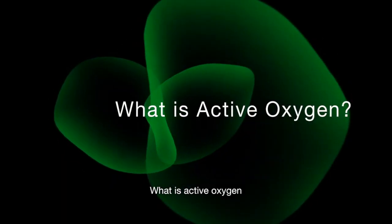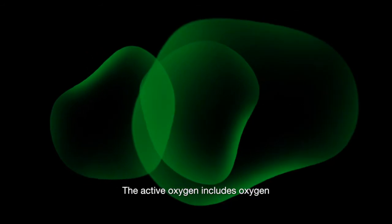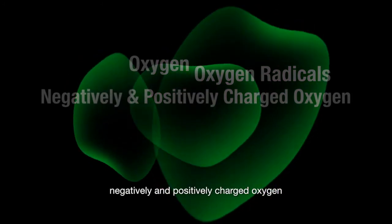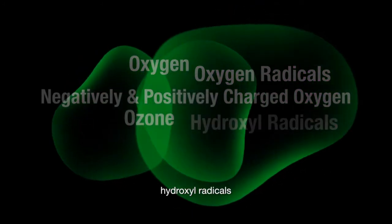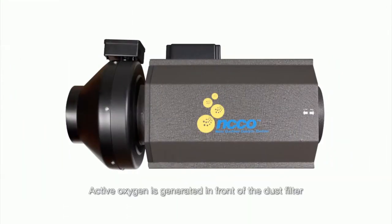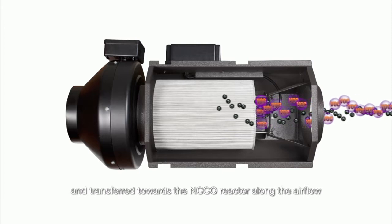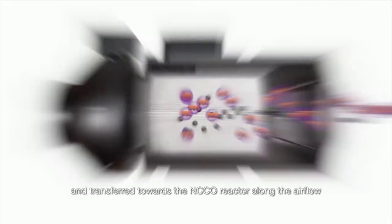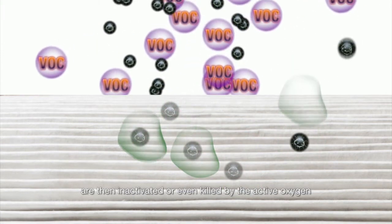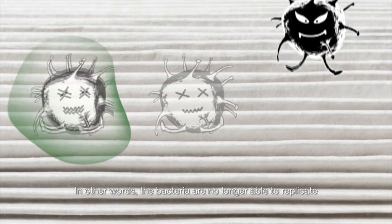What is active oxygen? They are highly reactive molecules with oxygen atoms. The active oxygen includes oxygen, oxygen radicals, negatively and positively charged oxygen, ozone, hydroxyl radicals, hydroxyl ions, and hydrogen peroxide. Active oxygen is generated in front of the dust filter by the active oxygen generator and transferred towards the NCCO reactor along the airflow. The trapped bacteria and viruses are then inactivated or even killed by the active oxygen. In other words, the bacteria are no longer able to replicate or threaten human health.